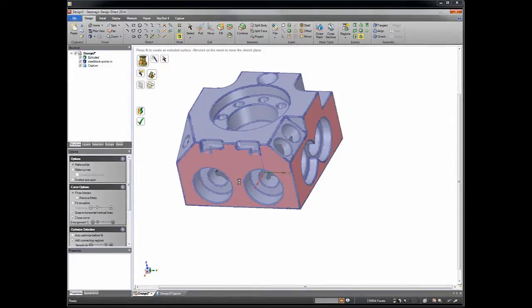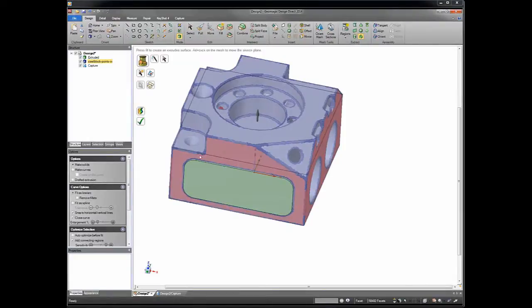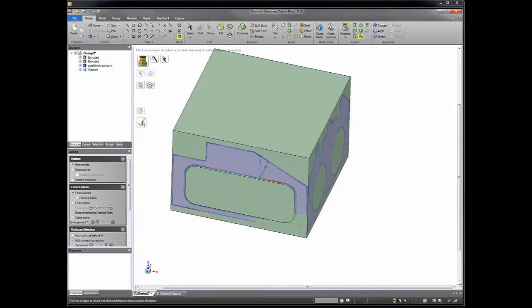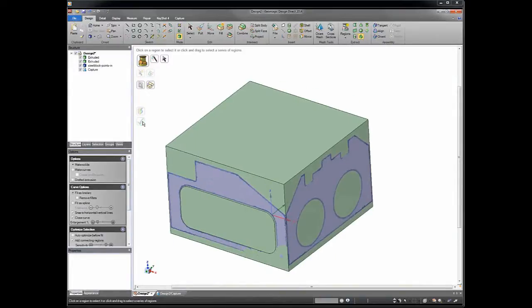And then you'll see a preview in a few seconds. It's like a black line that will indicate what my regions are. So you can see it's like a preliminary sketch. You can vaguely see that black line going around the outside, such that if I were to hit the complete button, it'll build the solid. Okay? So just by a couple of quick clicks on these regions, you can quickly create the solid.